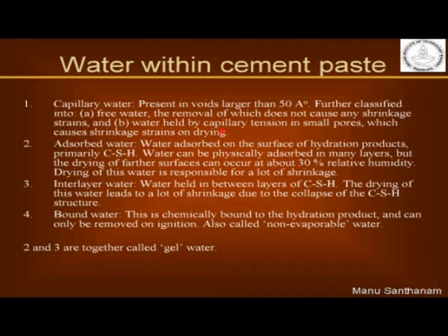Why is that? Again, you remember your basic physics, when you have very thin capillaries, you have a great rise of water inside the capillaries because the capillary pressure is high. When you have large capillaries, water does not rise inside very much because you have very low capillary pressure. Similarly, if you have a water filled capillary which is very large, if you try to remove water from there, it will not produce much capillary pressure, so your shrinkage strain will be low. But if you have a very thin capillary pore and you are trying to dry the water out, it is going to produce extremely high capillary pressures and lead to very high levels of shrinkage.